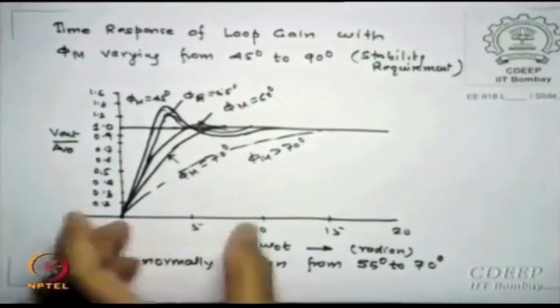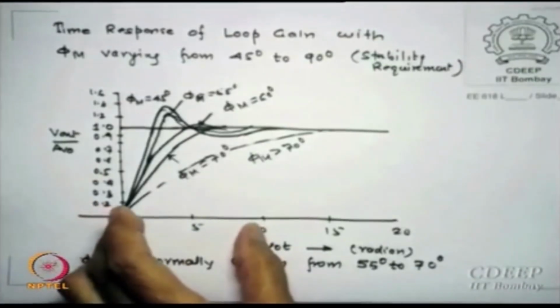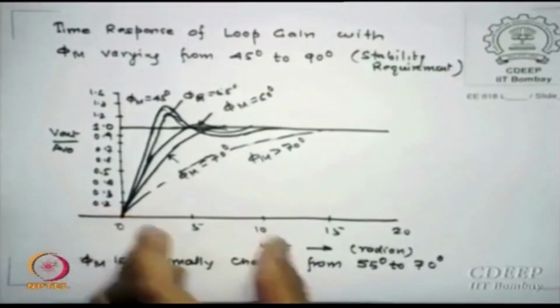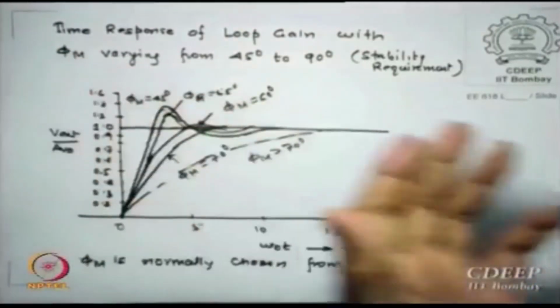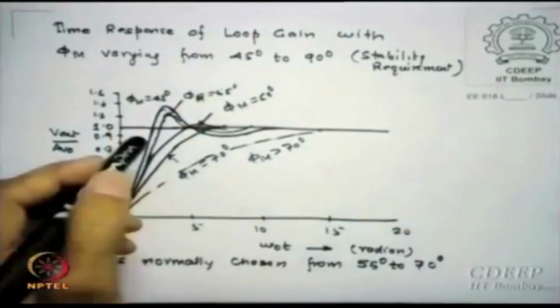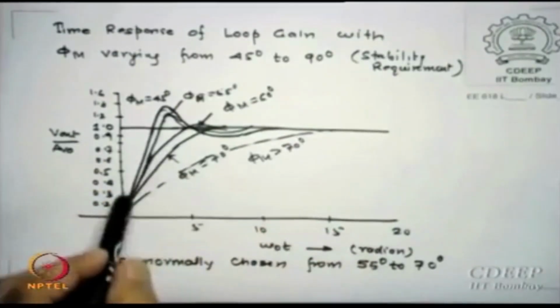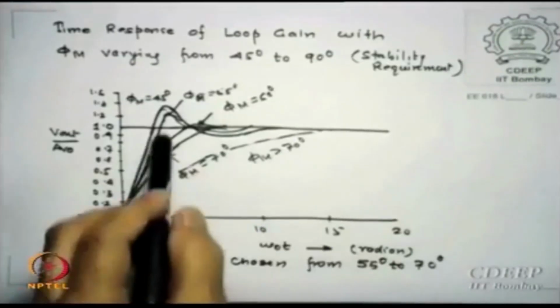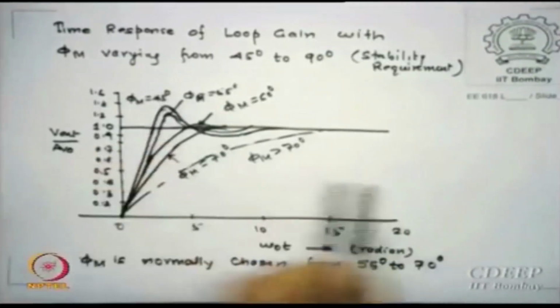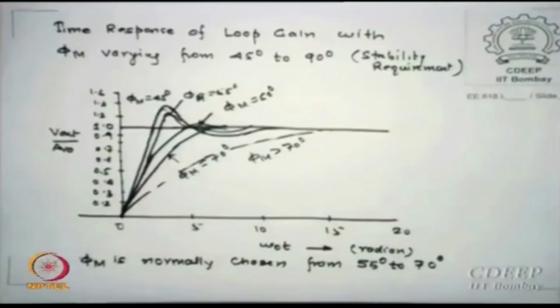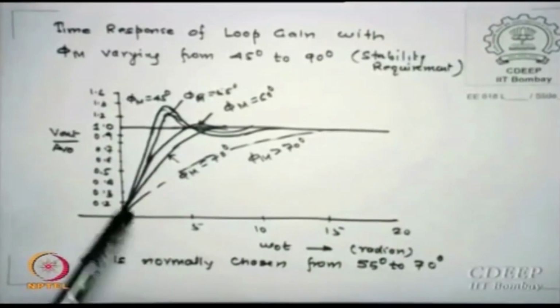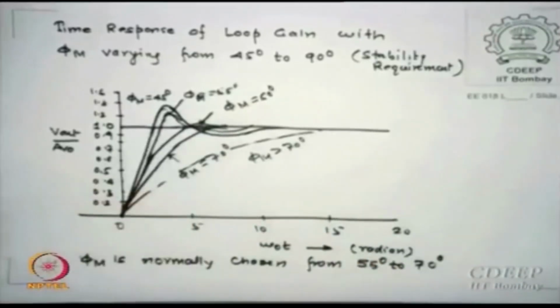Okay. So this will be a huge settling time. If I increase phase margin, which I did, of course these figures are not up to scale, they are just representative. If I go for 55, I figure out that the peak goes down and it also reaches the constant point faster. I have increased to 60, I find very little overshoot and it dies down very fast.